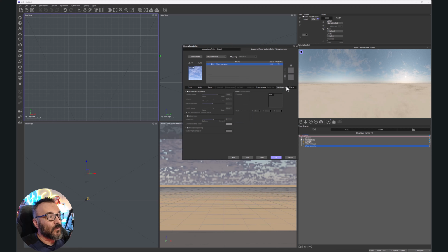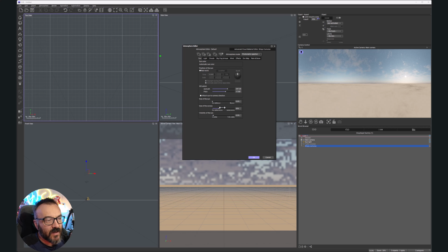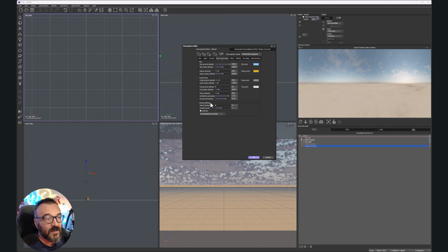then you want to go to atmosphere editor. You want to go to sun details here, and you actually want to hide: no visible sun, no visible corona. So it will erase it. You still have some lighting coming from specific directions. And to disable this, we actually need to go inside the glow and reduce some of the glowing intensity. That will remove it. And you can see it's a sky without sun.